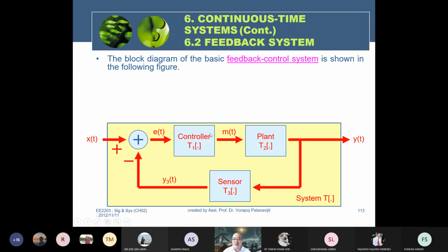If there is no error, it means the controller receives the signal that the room temperature is already matched to your setting. The controller will send the signal to stop the plant, to stop the compressor, for a while. When the compressor is stopped, the room temperature increases due to heat propagation from outside the room to inside. If the temperature reaches 26 Celsius, it has increased by 1 Celsius. It checks again.